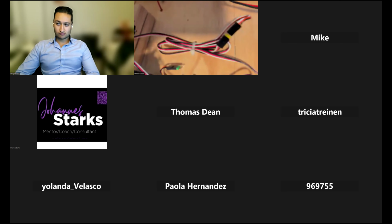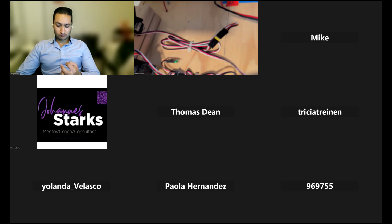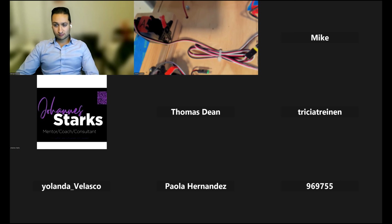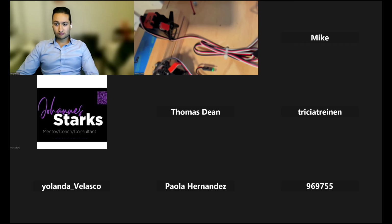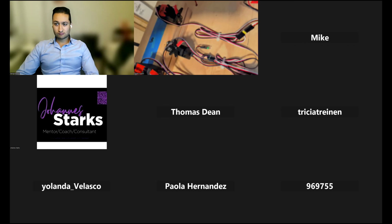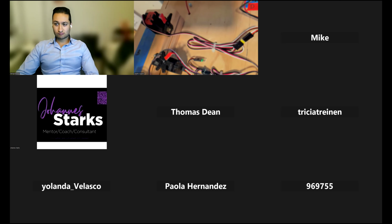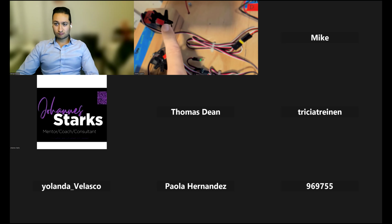And then on my table over here, I have a servo extension wire plugged in with a header pin. And if I press the A button on my remote, I can see that it's spinning. It's clockwise if you're looking at it from the front, about 45 degrees or so. General rule of thumb is that whenever you're controlling a servo like this in Best Robotics with the robot brain, you could get up to 100 degrees of rotation, give or take a little bit. So this is half of the rotation, that's about 50 degrees.